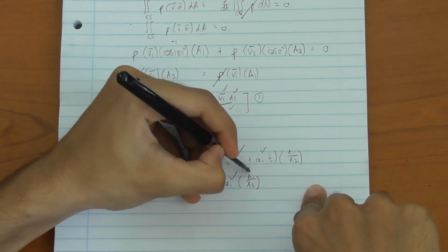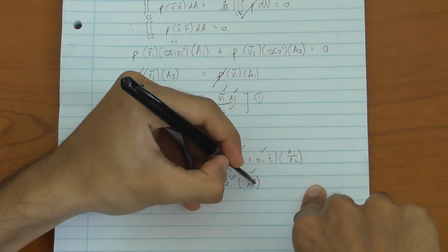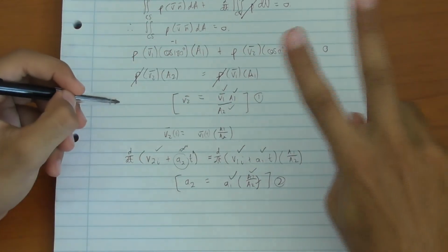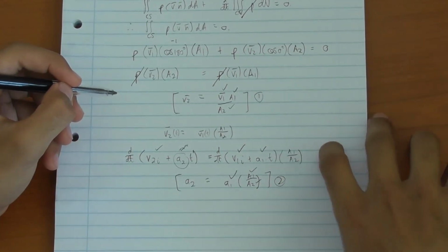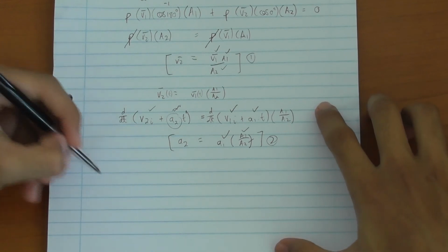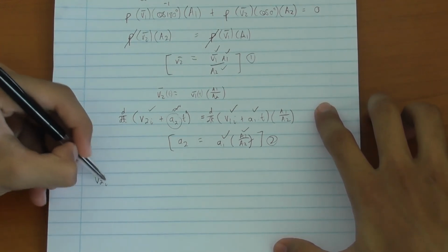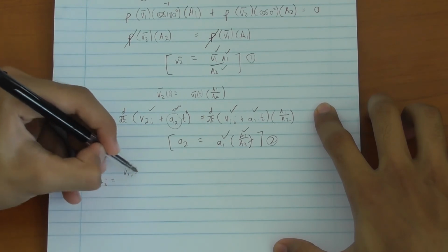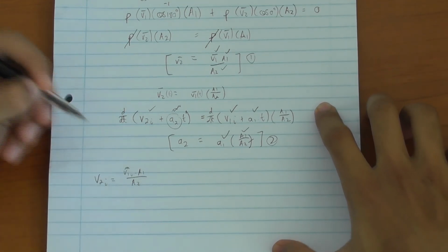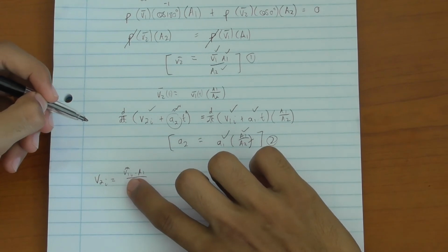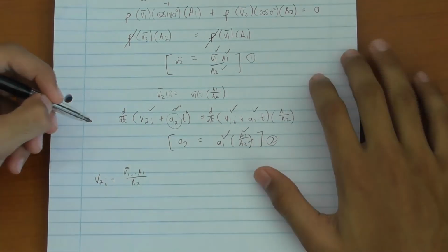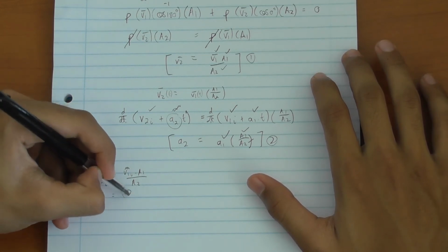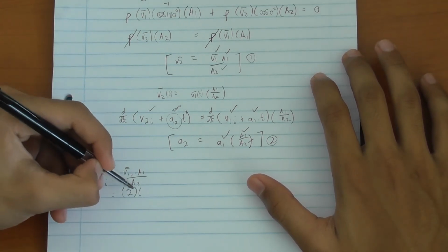So we know acceleration 1, we know area 1, and we know area 2. So you've now got 2 equations, 2 variables to solve for, and that shouldn't be too bad. So let's start substituting in some numbers. All right, so V2 initially is equal to V1 initial multiplied by A1 divided by A2. And the reason I remove the vector from here is because we're dealing with constant values now. So V2 is equal to V1, which is 2 foot per second, multiplied by area 1.